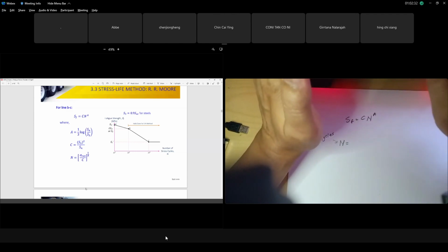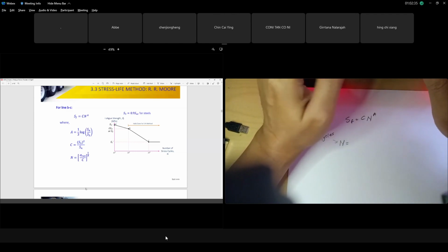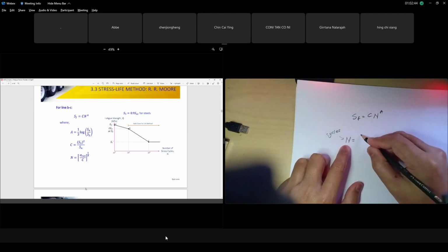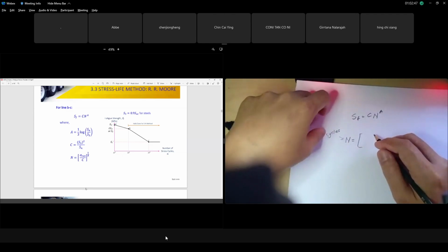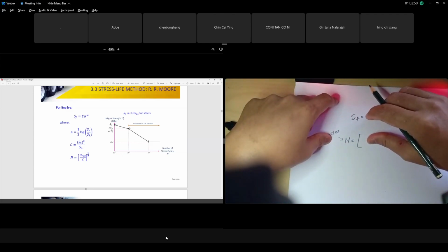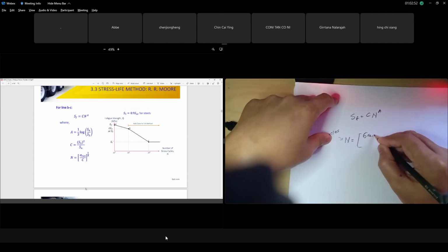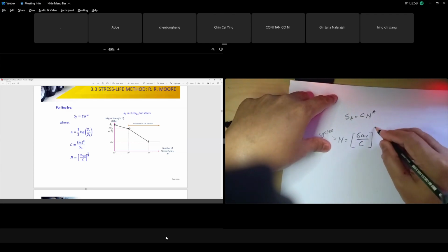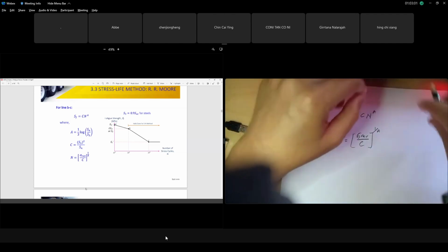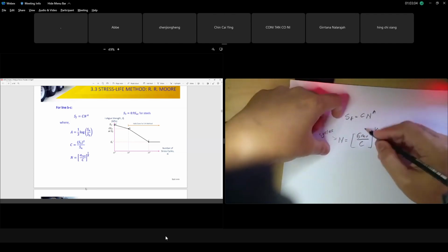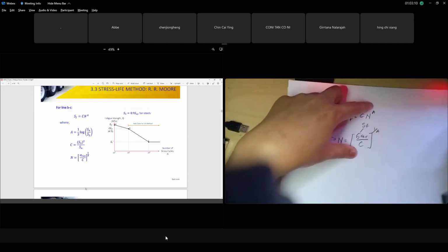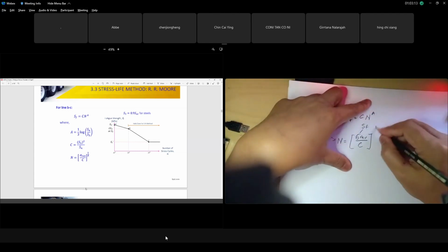That's why you calculate your static factor to be less than 1. Sometimes in an exam question, you find your static factor is less than 1, and they ask you for how many cycles, how many revolutions, it would break. So you can use the equation. If you look at the bottom equation, the number of revolutions is your stress, completely reversed, over C, to the power of 1 over A. So your revolution is actually your SF, the stress that you calculate, over C, to the power of 1 over A.